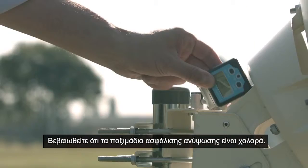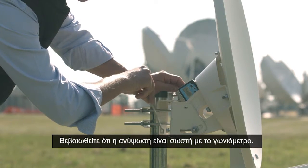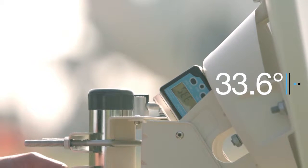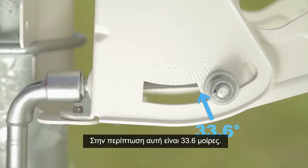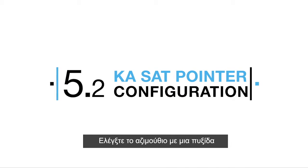Check the elevation locking nuts are loose. Check your elevation is correct with the inclinometer. In this case, it is 33.6 degrees. Check your azimuth angle with a compass.